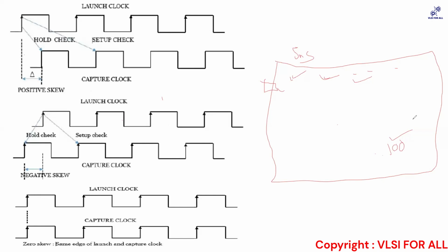If all of the clocks are reaching and all of your flops are switching at the same time. See, understand what a flop does. Once it gets the clock, your D pin becomes transparent. Whatever is at the D, it will go to your Q pin. Now understand that all 100 of the flops are switching at the same time. So understand the amount of power dissipation. It will be very high.